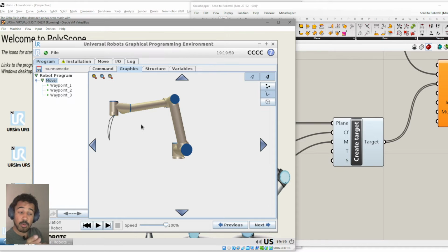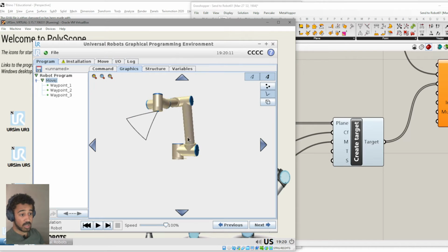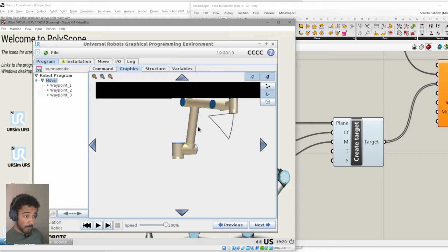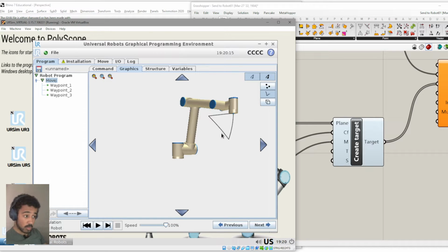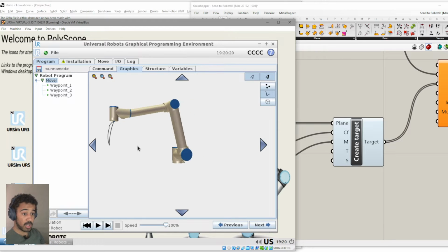It's much easier for the robot to actually move in this arc motion than to move in a linear motion. If it moves in an arc motion, it needs to have much less control over each of its axes, and can also be much quicker to reach certain points. We also don't get into singularities as easily as with linear motions. If you don't know what a singularity is, don't worry about it for now. You will probably find out sooner than you would like.